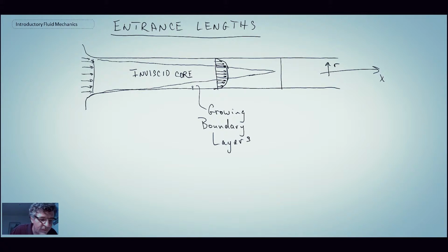developed flow. And here, the velocity, I'll try to sketch it in, assuming it's laminar for Poiseuille pipe flow. Maybe a parabolic shape. That doesn't quite look parabolic, but it should be. Let me clean that up. That line is not good. So it should be a parabola. That looks a little better.